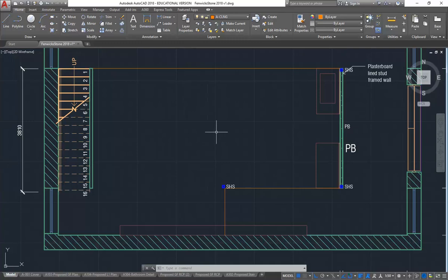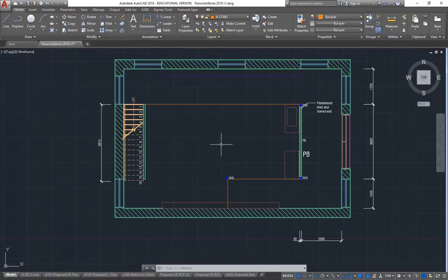On yours, most of you aren't going to have bedrooms on the ground floor, I'm assuming. You do? You don't? No. Okay, so if you've got a bedroom on the ground floor, just remember you always need a smoke alarm between the sleeping areas and the living areas. That's the basic rule.